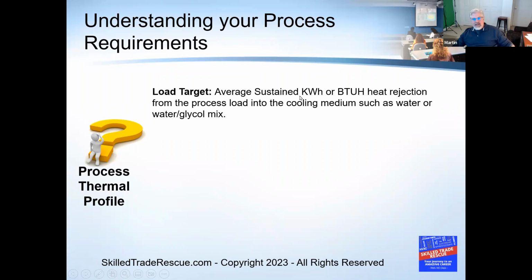This can be a little bit of a challenge because if you're cooling a piece of equipment that's been manufactured, you are in pretty good shape, because a lot of times the manufacturer that makes that machine, I'm thinking about a laser or one of these high pressure water cutters, things like that. If it's made here in the US, typically you can open up the site prep guide and find out how many kWh or BTUH is being transferred to the process fluid at max Q, max load. All right, so that's a big deal.